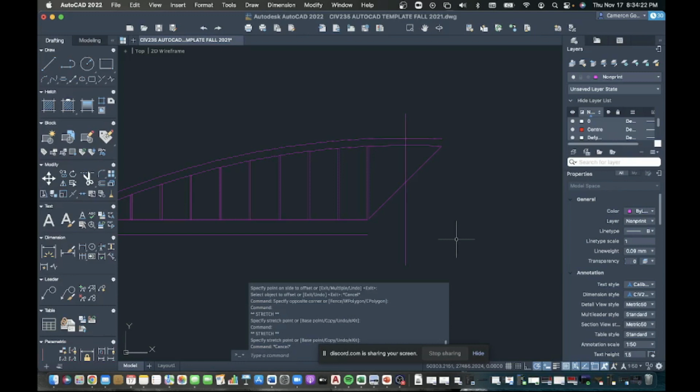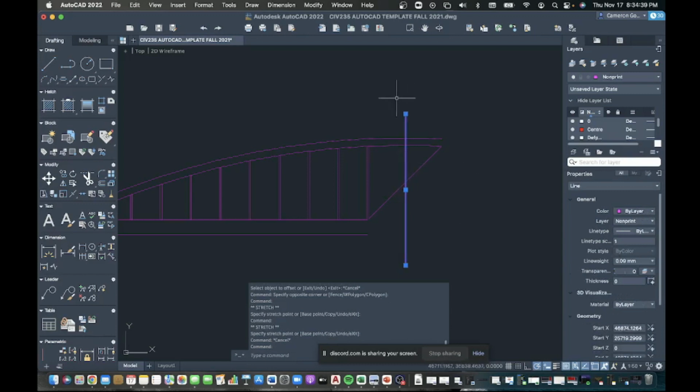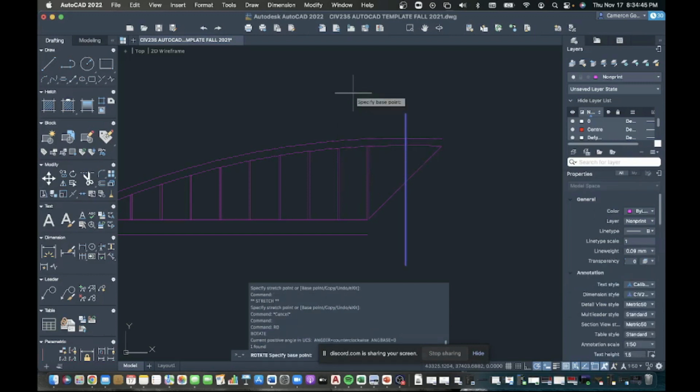Next, we're going to rotate the line 2 degrees from the intercept with the bottom of the arc, and that's going to look like this. So I'm going to go over the rotate command now. So our rotate is RO. I'm going to type RO, and so I've already selected my line rather, my shape.